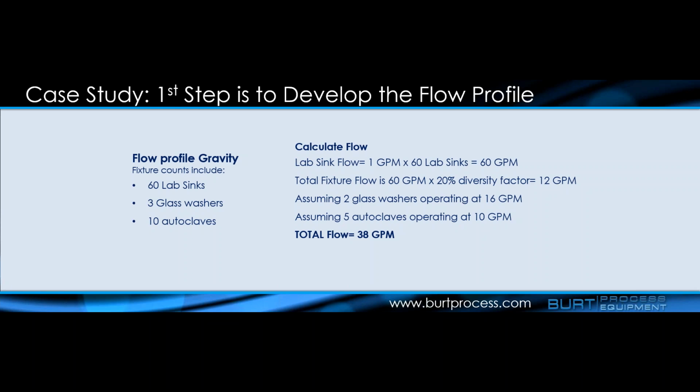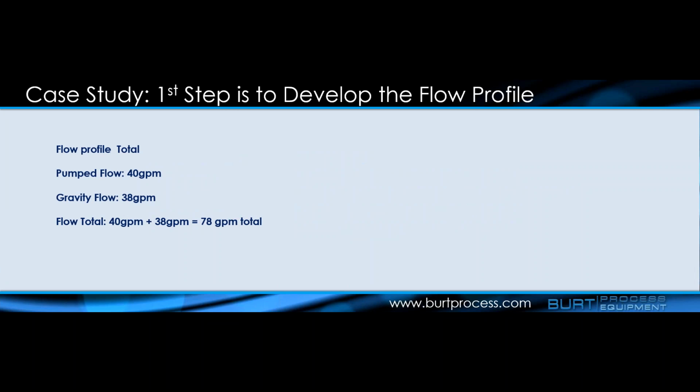So we end up with an estimated flow less than we would for the reduced fixture counts from our pump system. However, we always know that the pump will activate at that 40 GPM, so we have to account for that in our pH design. This is where we have to take a diversity. This is what you're generally going to see coming into your system.